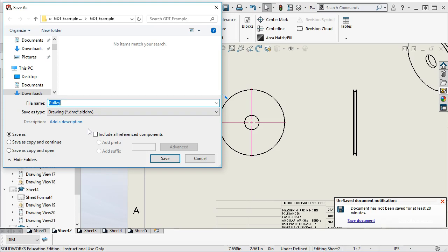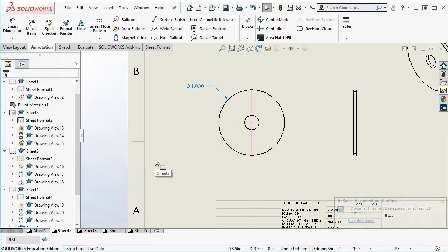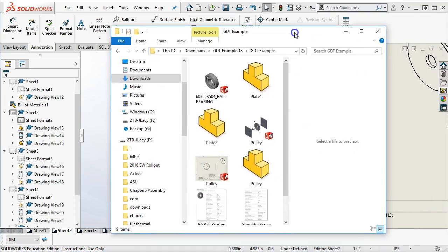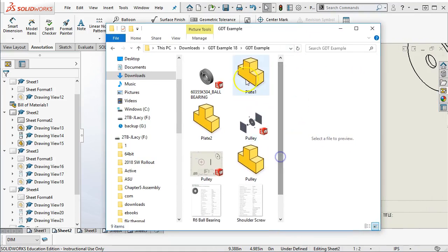So at this point, we've created pretty much all 3 of our modules. We have the part files that were originally virtual components inside of the assembly, created in that assembly file, the SLDASM, and then that produced the part files, SLDPRT, and now we're saving this drawing package out to the SLDDRW. So when I hit save, and if I'm staying consistent with my naming convention, which is whatever I want to call it, then I will end up with the symbols that in Windows show up as the parts, and also the document that shows up as the drawing preview.